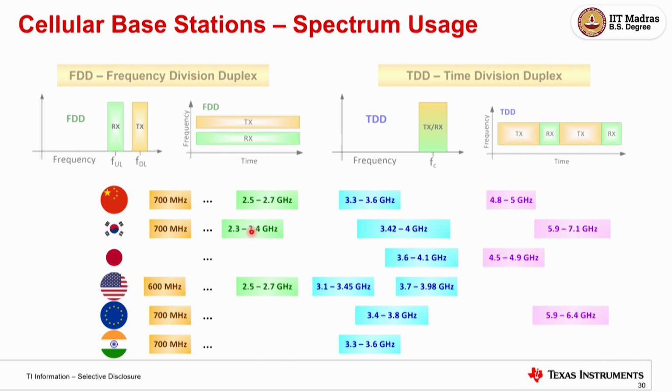And you can see somebody else, China is at 2.5. So for doing all this, you need those filters specific to the band, you need this PLL specific to the bands. But what the RF sampling, the last architecture, enabled is that if you're able to do everything together, the same hardware can be changed by software, because on a DSP you can do an upgrade of the software or firmware.